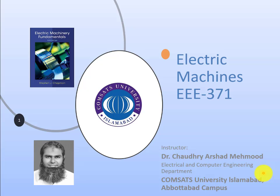So we are continuing with our topic induction motor. In the previous video we have seen the basic principle of the induction motor, how the torque is basically produced in it, and why it cannot run at the synchronous speed, but there is a relative motion between the synchronous speed and the rotor mechanical speed itself.